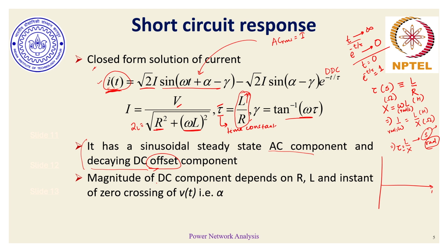So essentially, to find the RMS value of it, we would take the maximum possible value of current that this DC component would contribute. That DC maximum value is root 2 I. Root 2 I does not have any periodic behavior with it. It can only decay. It cannot change or have periodicity with respect to time. So the DC RMS, which is the maximum possible value that can appear, would be root 2 I.